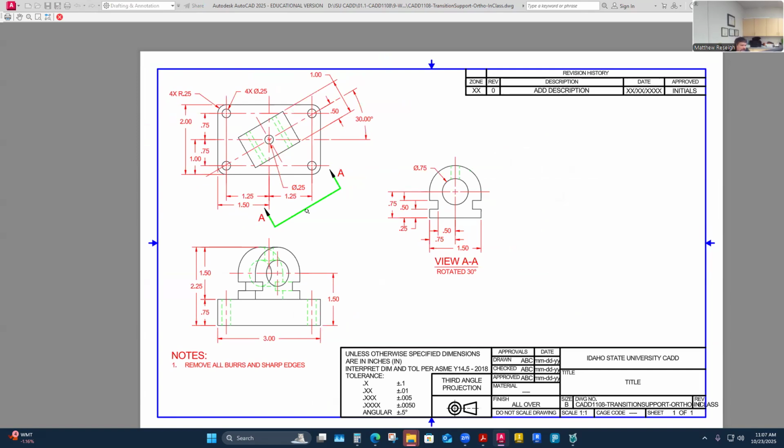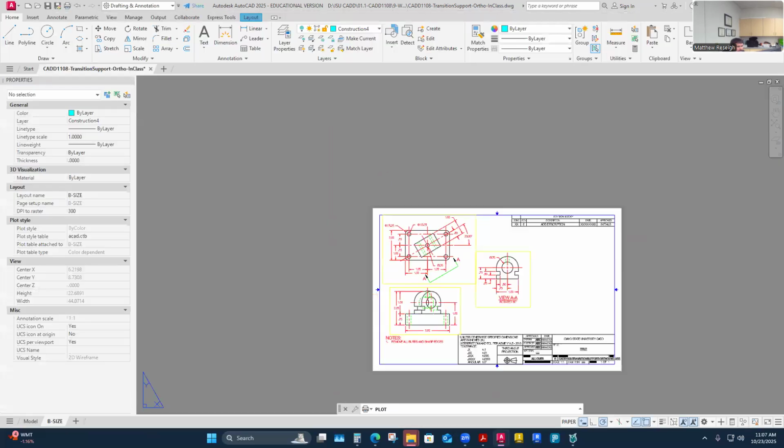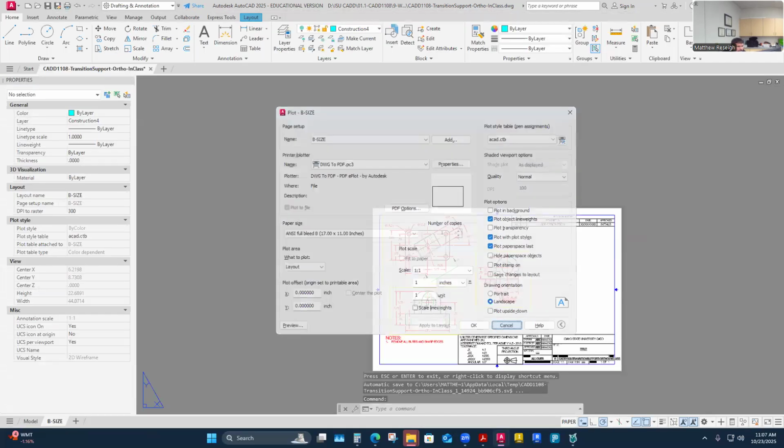And I didn't really realize it until I did this. I'm like, oh yeah, I can see my center lines need refined. My view plane, I need to see it break up. So it's too coarse. It looks solid and it should have some breaks in it. So let's go do some line type scale. That's when I usually notice when center lines and extension lines are not overlapping correctly: once I refine the line type scale, I'll see the breakup, and if I don't see it, it's because my extension line is usually going across too much still. So it's one of my indicators when I adjust line type scale.